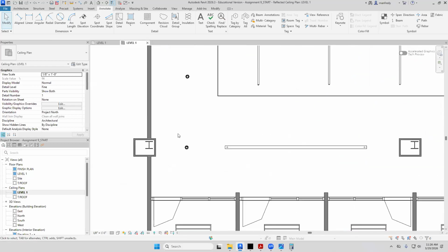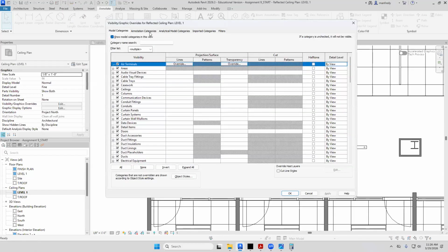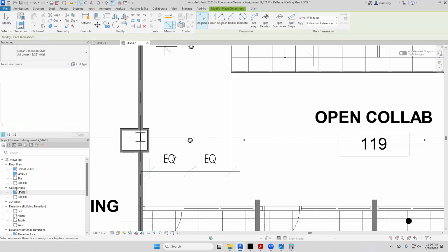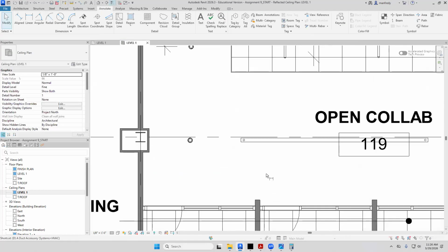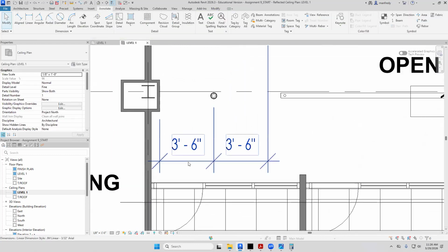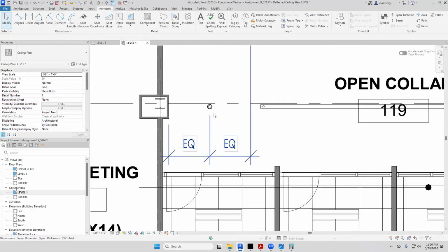So that is when you go here and you measure something. Make sure I turn this on. If I want equal, I would do a measurement from here to the center. It finds the center automatically, to here. And if I want that to say equal, I would click on this. And you see right there it says equal. If I click on that text, it shows equal. If they're not equal, it'll move the light and make it equal.